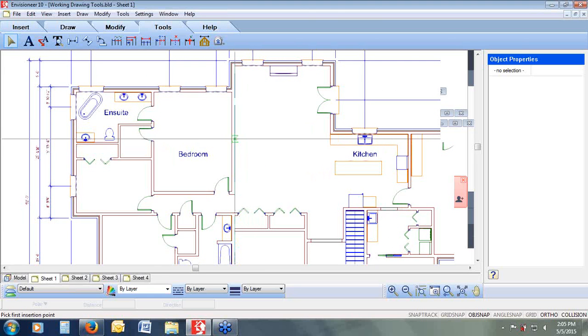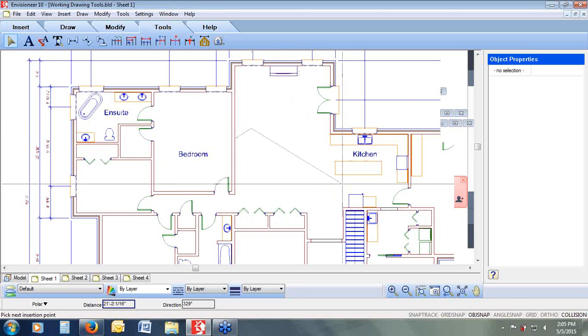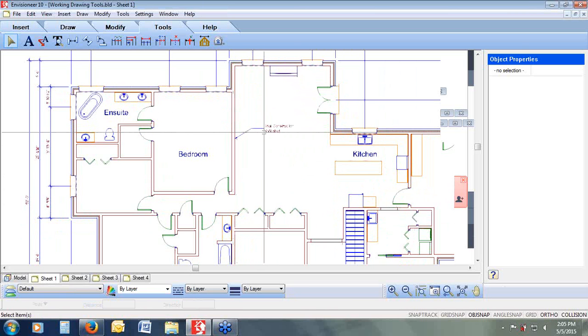reside. So I'm going to point to the wall, left click, move my cursor, it's a 2-point arrow. So at this point, if I wanted to turn ortho off so I could come up on an angle and then turn ortho back on so I'm coming straight across, I can do so. Or I could have picked both points right in line to have one straight leader. So text puts in our text wherever we want it to go, and text with a leader first allows us to draw a leader so that we're pointing to where we want the text to go. Two different types of text.